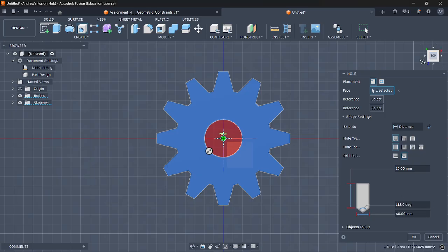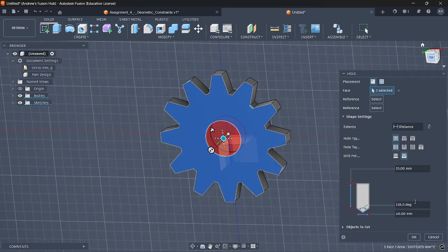This is a really thin part, so it's kind of hard to tell, but if I change the depth to like 5 millimeters, oh, that's the diameter. If I change the depth to like 5 or something, you can see there's that taper on the bottom, right? So that's a little bit more information for the machinist, but also for you, right?